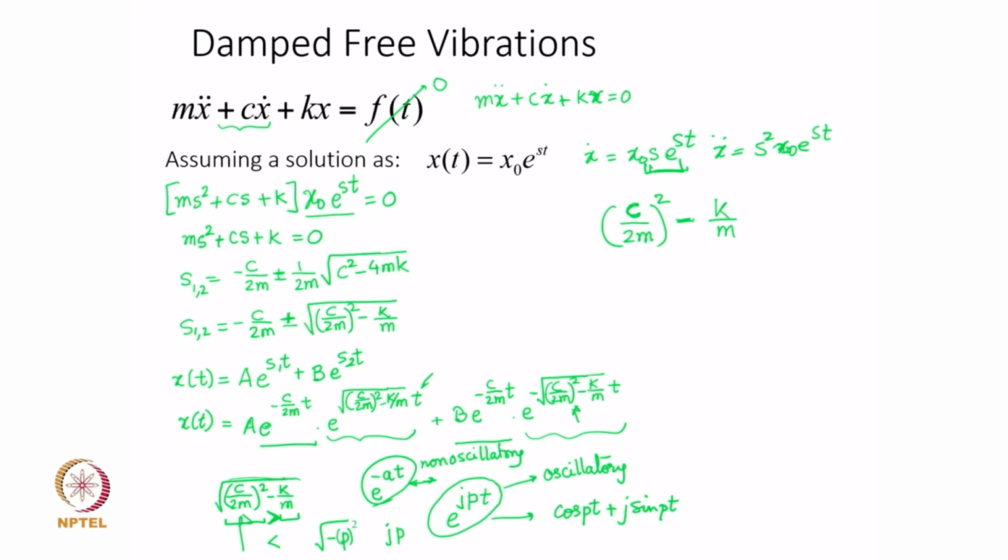So, what we do is we take a threshold value of this C by equating these two terms. If these two terms are equal, then the whole will be 0. So, it is sitting at the threshold of being oscillatory to non-oscillatory, and when you do that, I call this damping term the critical damping term, because that is the value of the damping coefficient which is at the threshold of the system turning from oscillatory to non-oscillatory or vice versa.